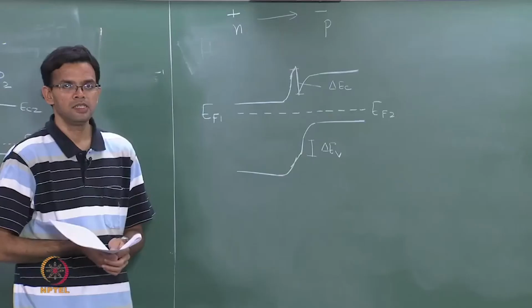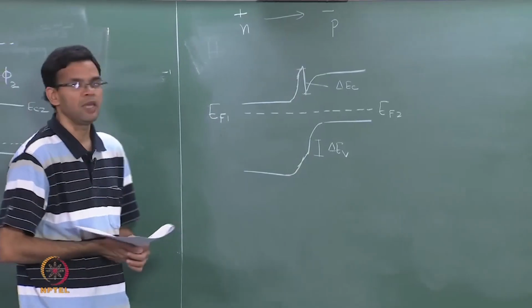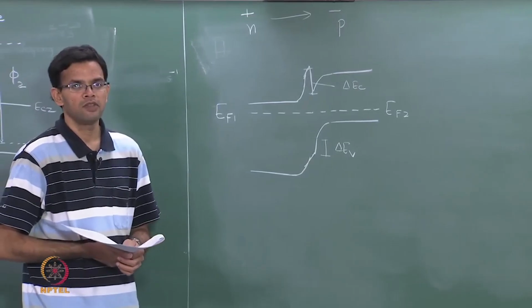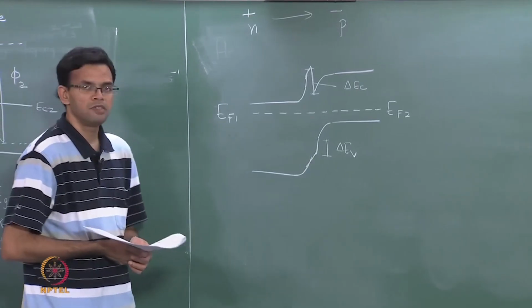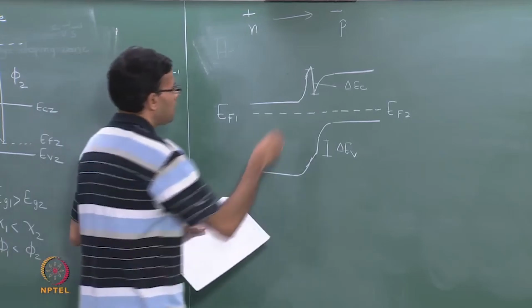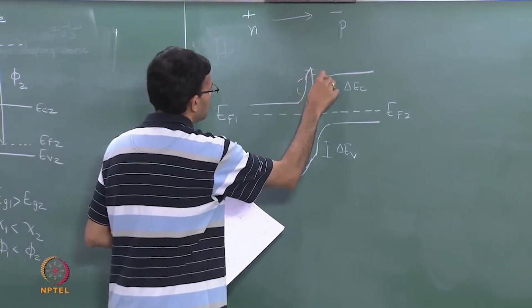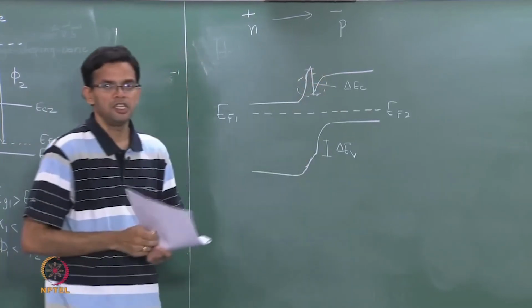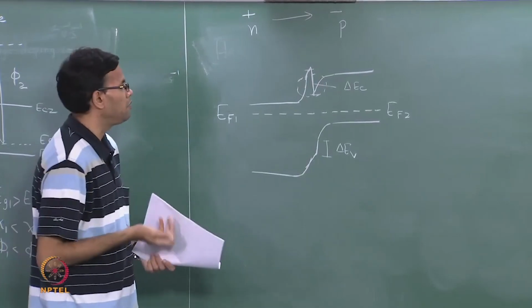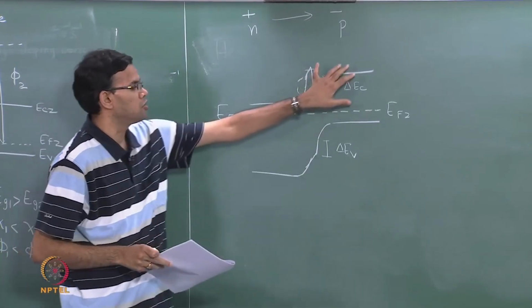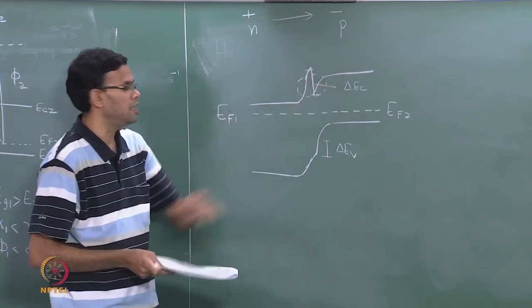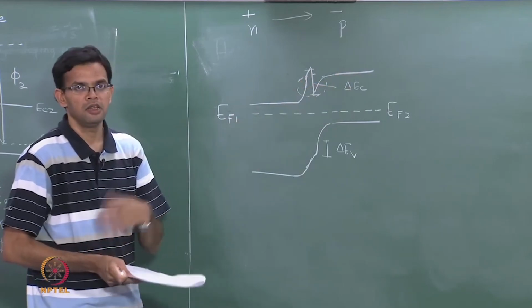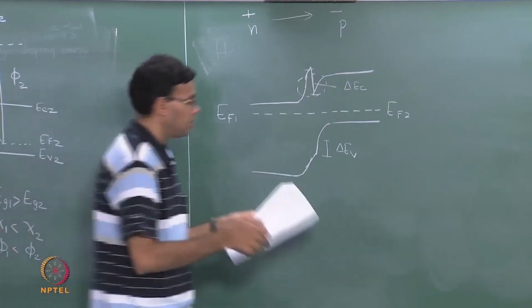So, if you look at this, this is different from how a p-n junction would look if you have the same material. Specifically, if you looked at the conduction band, there is a region where there is an energy minimum, so that electrons in the p side can essentially accumulate in a region near the junction.